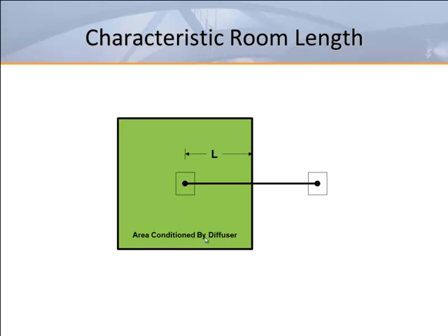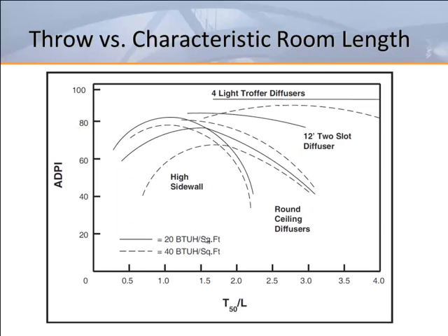The L is the distance from the center of the outlet to the shortest edge of the module served, or 1/2 of the distance between 2 outlets. L is based on a 9-foot ceiling height and can be adjusted for lower or higher ceiling heights up to 12 foot. For example, when the ceiling height is 10 foot, add 1 foot to L.